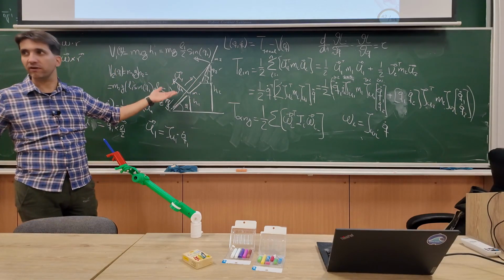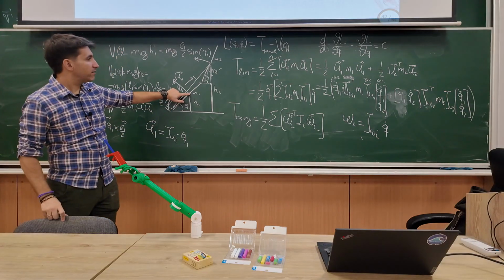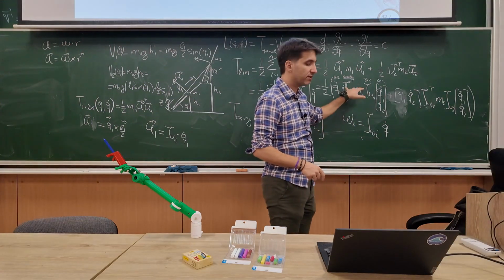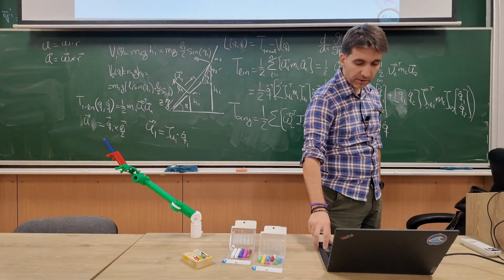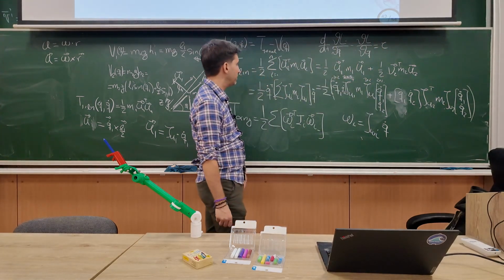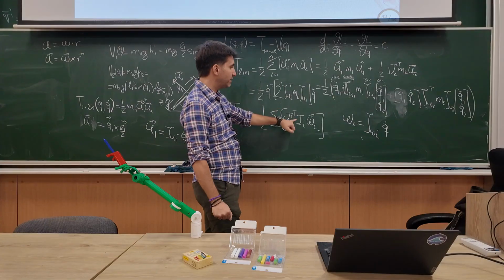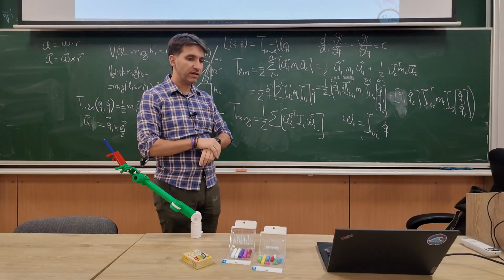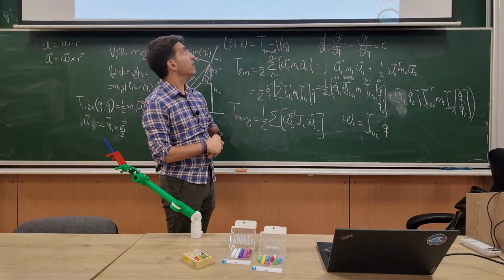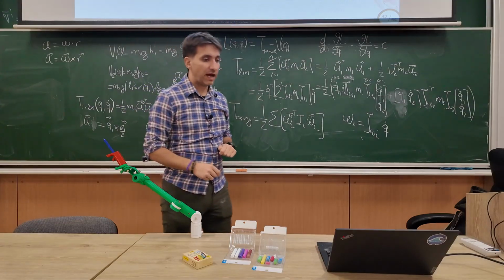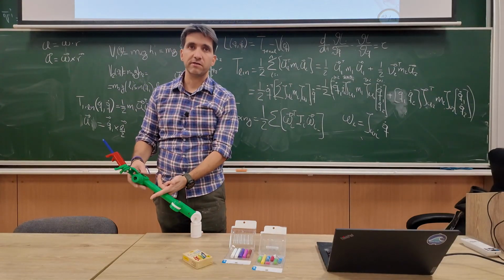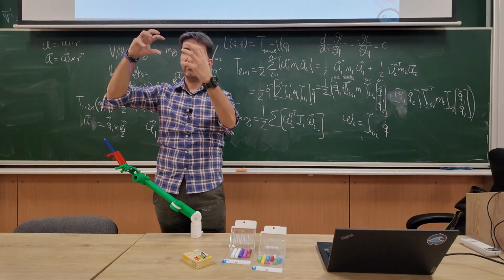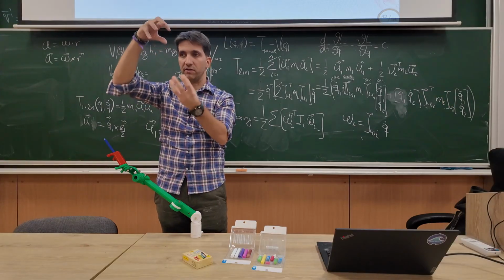Why did we have to bother figuring out the Jacobian? All right. Again, I have to do the padding, so the dimensions of the Jacobians are the same and the Q's are the same, but eventually I will end up with a similar form. One little detail here for the moments of inertia, and it's why I wanted you to understand a little bit what the moments of inertia are about. These moments of inertia, this I, they're expressed in a frame attached to the link itself. Like we have an object, we know the inertia in a frame attached somewhere in the object, right?